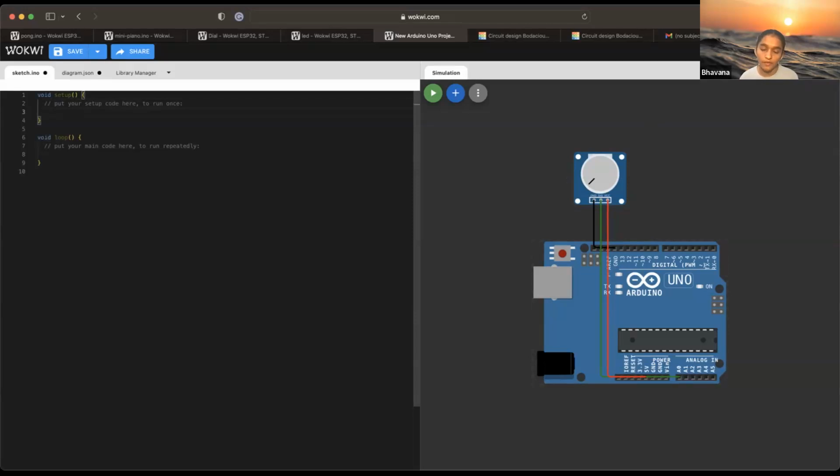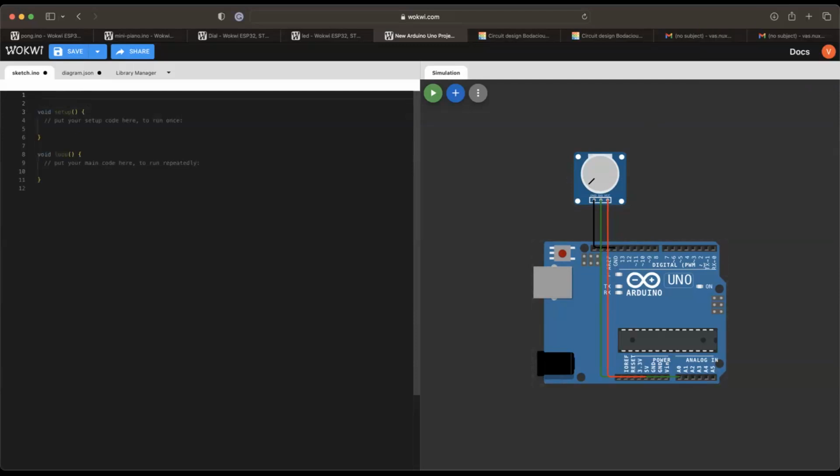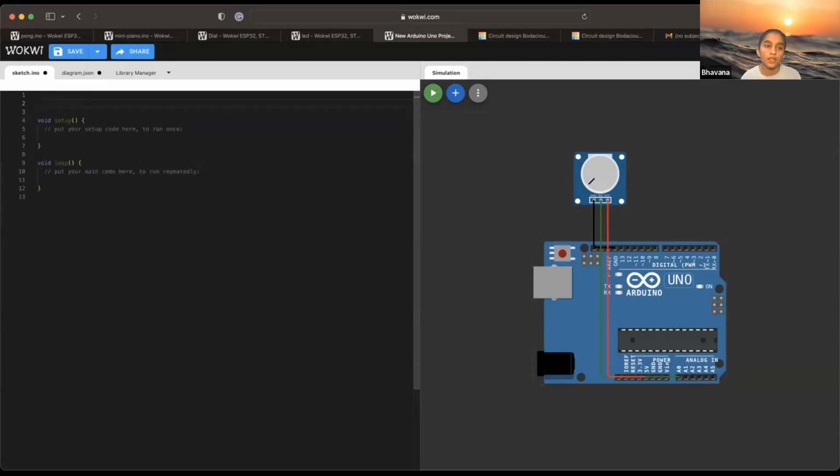And then the coding gets a little complicated, but it's okay. We have variables in programming, and we're just going to make 3 variables. Variables don't have to be in any of the functions, so I'm getting out of the function, and then I'm going to type const. Do I have to delete the void setup? No, you still need those. We're just going to use the variables first, and type everything in setup and loop later.